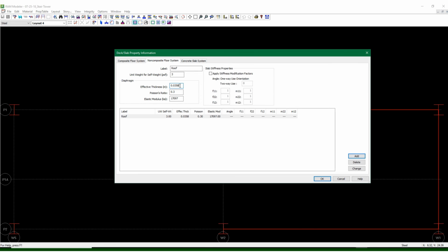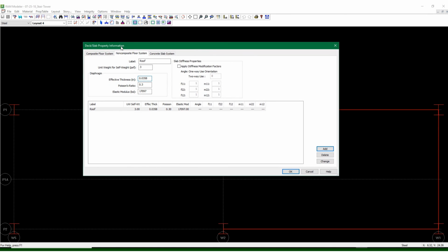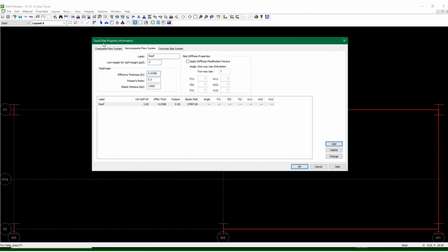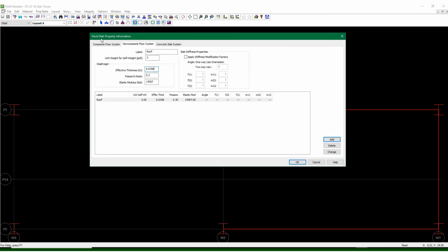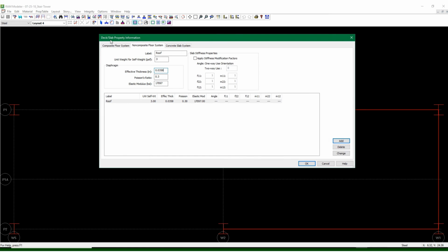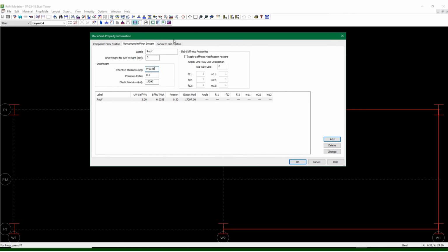Type B roof deck. I typically use a 20 gauge, not a 22, just because welding is a lot easier with the 20 gauge than the 22. Even though 22 is weldable, sometimes you get burnout depending on some of the settings that the welders have on their machines, and you need to use welder washers in that case. Just for the record, welder washers are recommended for decks that are really thinner than a 22 gauge. But in my experience, even 22 gauge burns out sometimes.